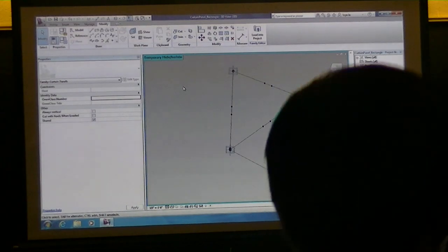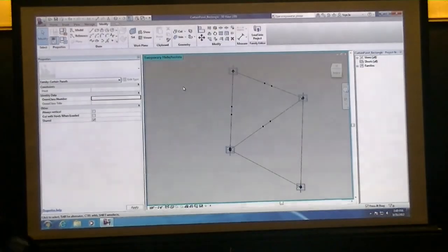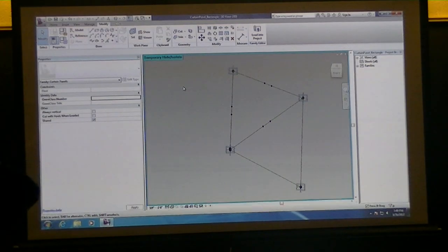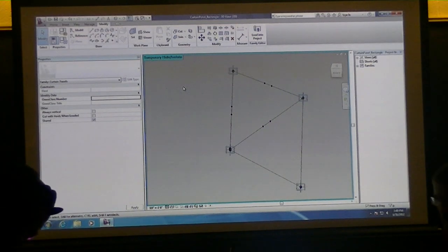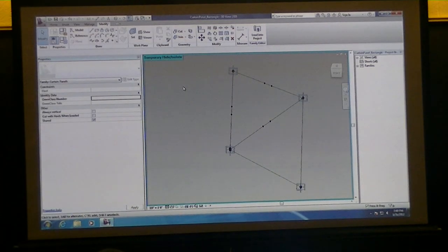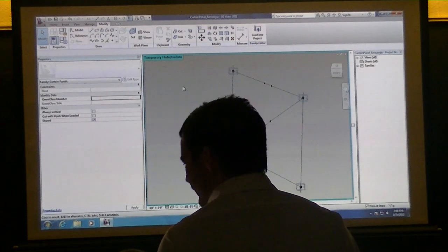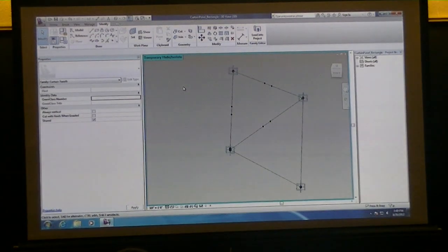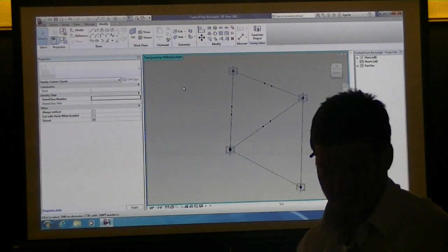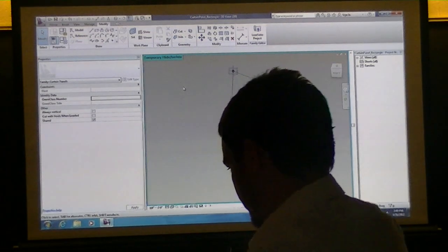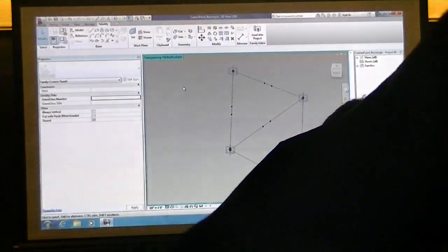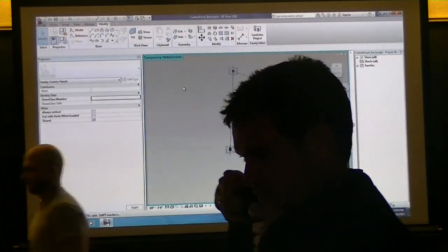So just one surface. Okay, that's it. I wasn't able to get the ends for some reason. We were just doing a semi-circle, and then they created one direction. Okay, so go through the steps again. What you want to really make sure is that your lines extend past the half circle that you created. If you snap to the end point of your line, it thinks you want to extrude that as a form. But if it goes past it, it thinks that it's an axis and will revolve around.